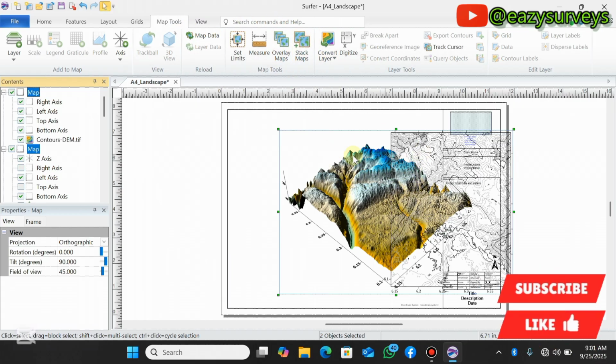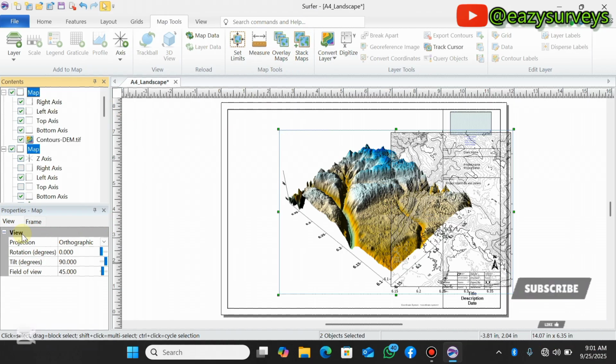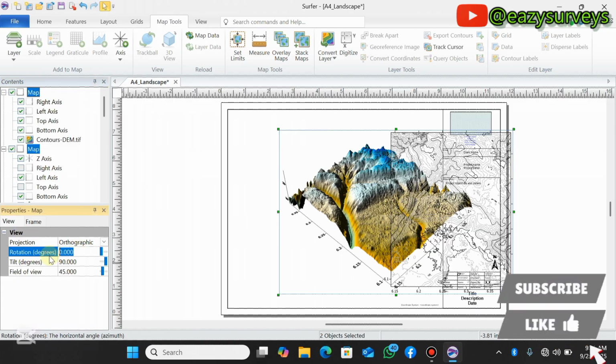So the two maps have been stacked, but you need to change the perspective projection parameters. After you click on stack map, under your properties the map will be activated for the view. What you need to do is change the rotation degrees. I'm just going to go with 300 for the rotation degrees.